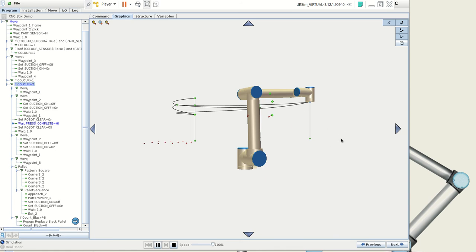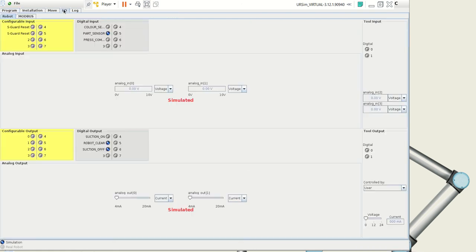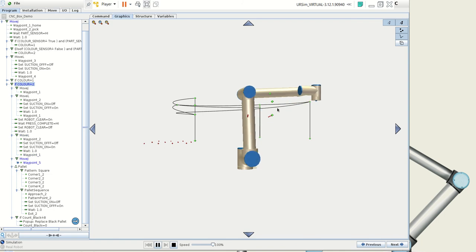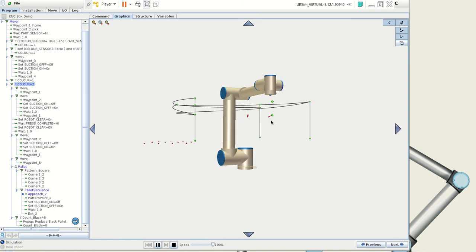on the other I/O. Then that knows the robot's out of the way, so it can go ahead and do its pressing or whatever, and then when that's done, it sends an output back over to the robot, which will ultimately get an input, because if the other machine sends the output, it will come as an input then on this transmit receiver sensors. So if I say okay, the press is complete, you'll see the robot will now go pick up the part and then bring it into its palletizing location.